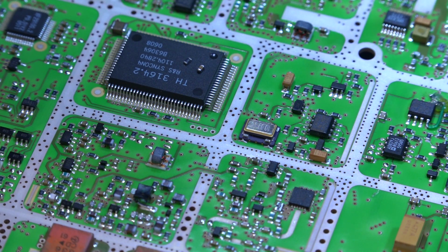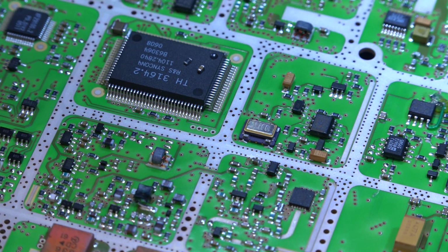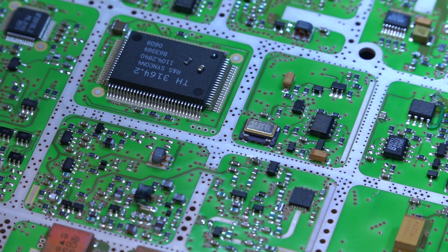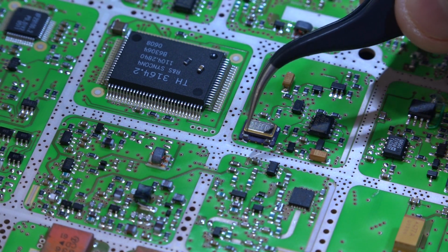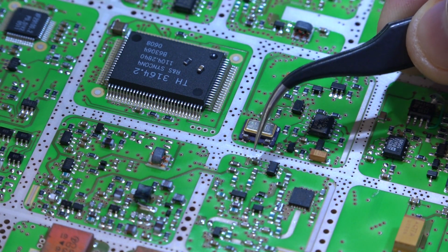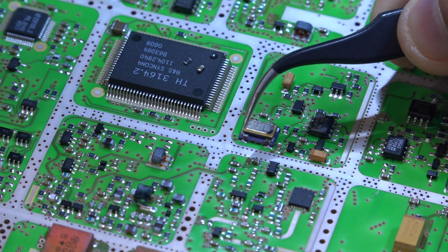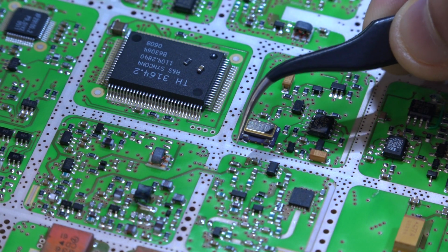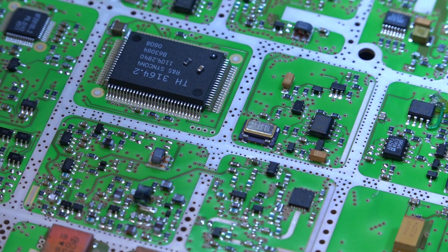So what I think was going on was that there was a flaw inside this capacitor, potentially an ohmic contact, causing maybe 10 ohms or so. And that was causing the entire structure to draw a lot of extra current in order to supply the current for the frequency divider as well as the DC current that was going through the capacitor. And that over time heated up and aged this 1 ohm resistor, and I think it eventually died.